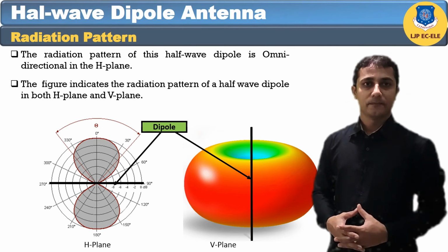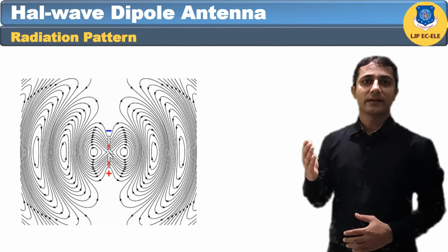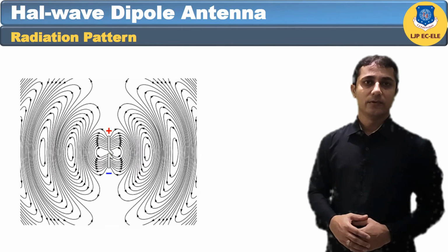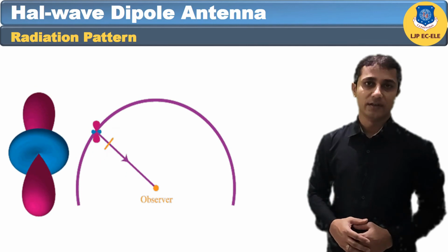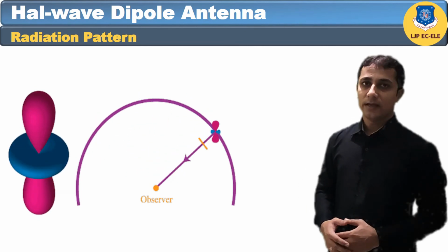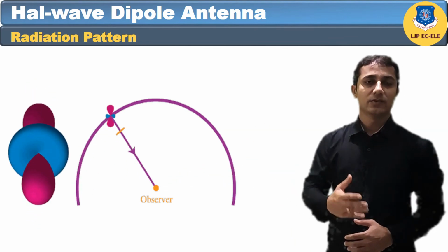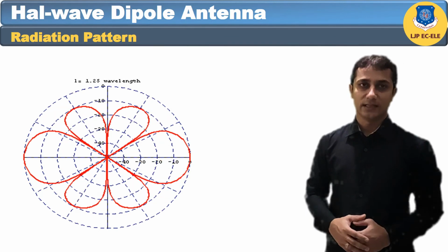Now, the radius of the dipole does not affect its input impedance in this half wave dipole because the length of this dipole is half of the wavelength and it is the first resonant length, and an antenna works effectively at its resonant frequency which occurs at its resonant length.